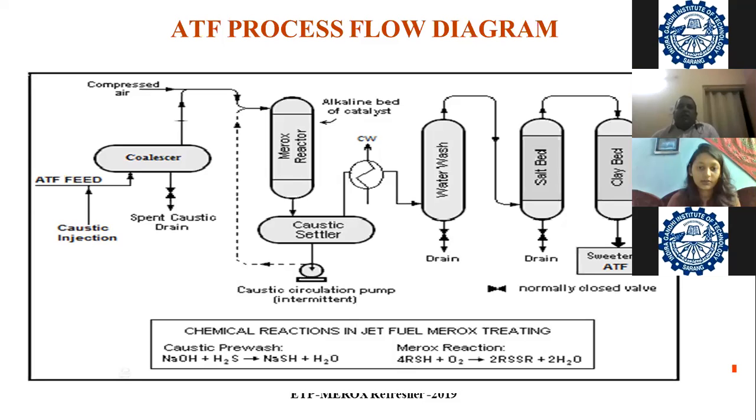When we are talking about the fixed bed reactor, it indicates that there is a fixed solid carrier for the Merox catalyst. What is the solid media of the carrier? That is called activated charcoal. Activated charcoal is to absorb any traces of impurity constituents present in the hydrocarbon, such as phenols, naphthenic acids, and basic nitrogen compounds. These trace constituents are likely to interfere mechanically with the performance of the catalyst. Caustic is continuously leached out from the bed along with the traces of impurities. When the spent caustic color appears dark brown, it indicates that the reactor caustic is to be dumped and spent, and charged with a fresh circulation of caustic to keep the depleted catalyst bed saturated.